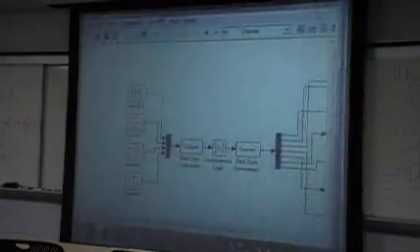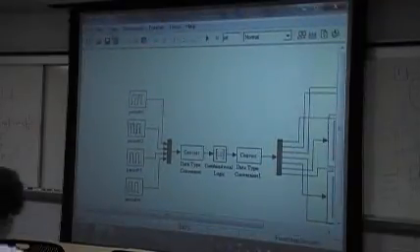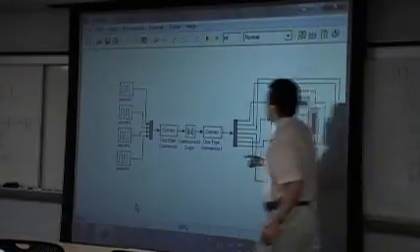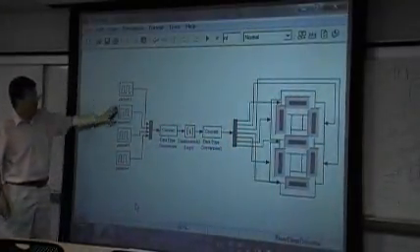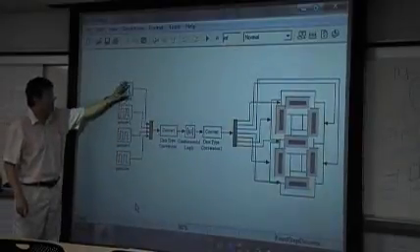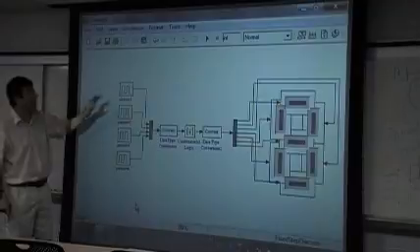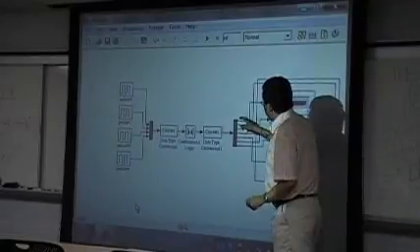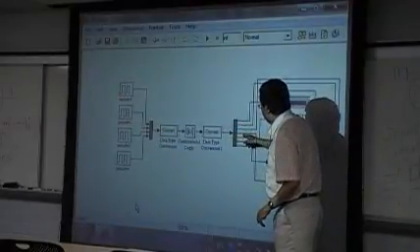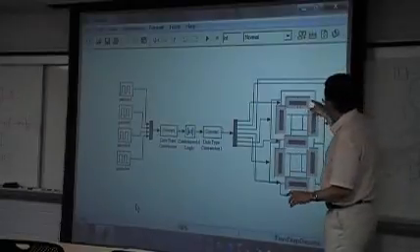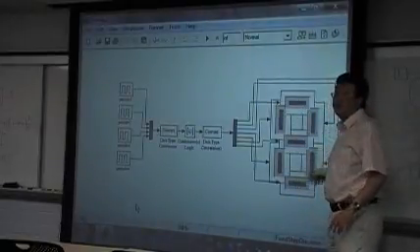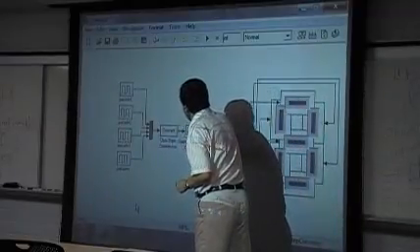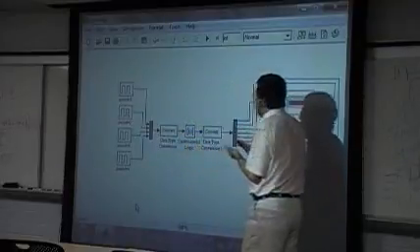So this is the block diagram I want to create. In the block diagram, we have 4 input signals, and these input signals are generating binary signals. I will explain this part to you later. There should be outputs to drive the 7 LEDs, and I can arrange the 7 LEDs in a shape like this. And here we have to implement the truth table for that kind of decoding.